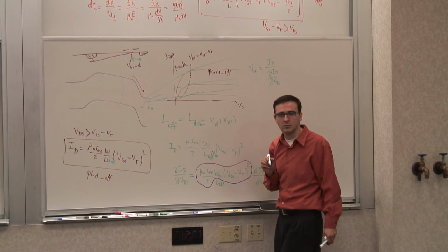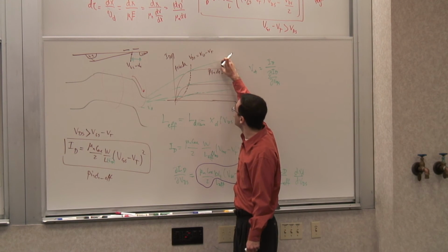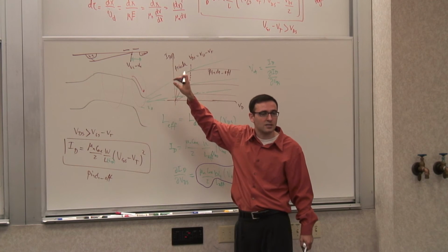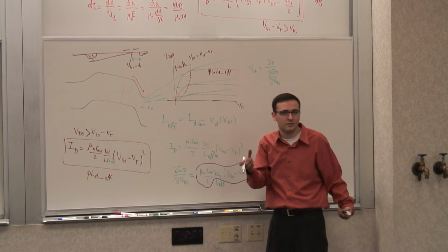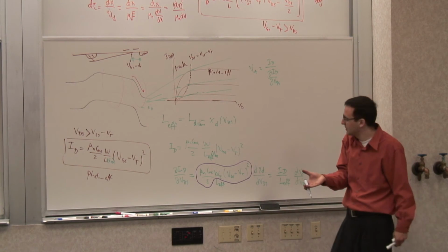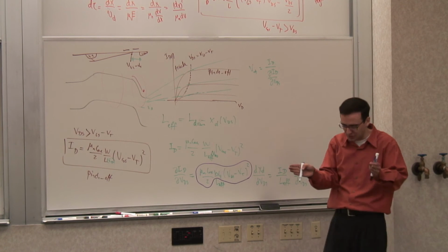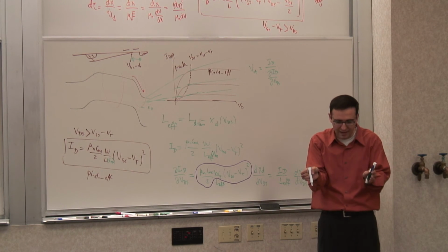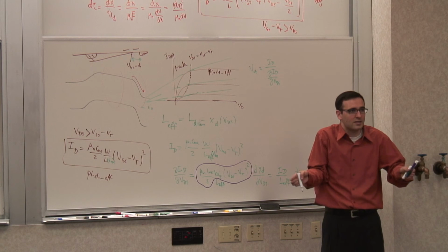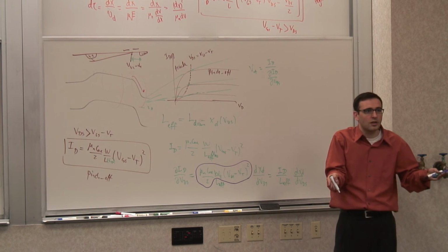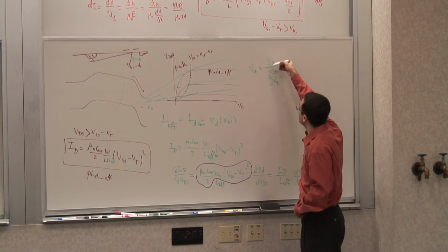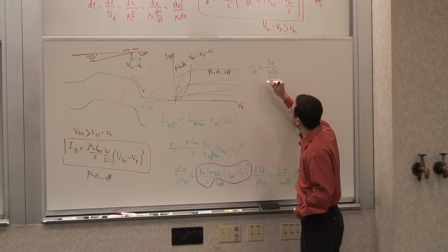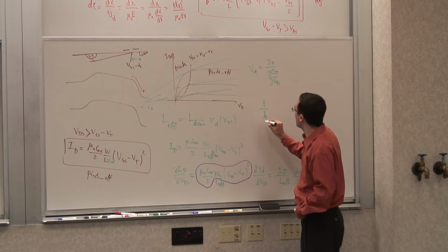Because we saw the larger the current, the larger the variations. The fractional amount of variation is fixed. If you double the current, the same change in VDS results in the same fractional change in the current, which is twice as large in absolute terms. So this should be a constant quantity. So you can define a similar thing for MOSFETs, actually defined as 1 over lambda of L.